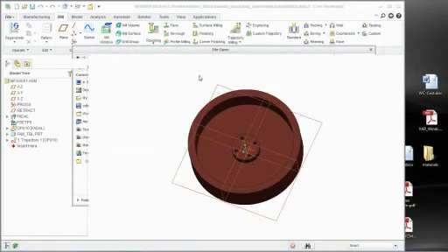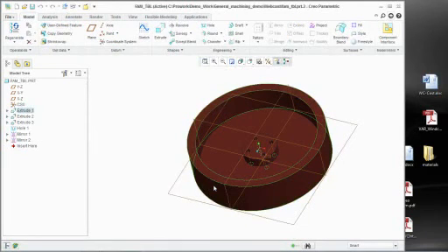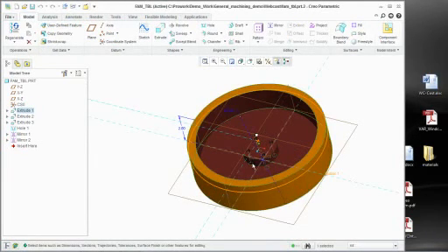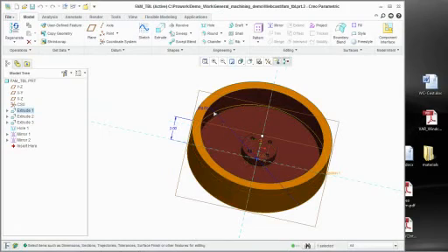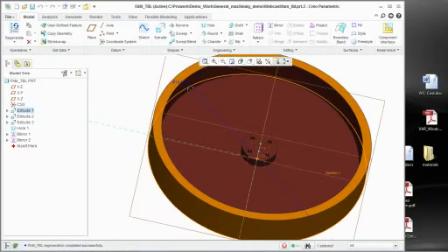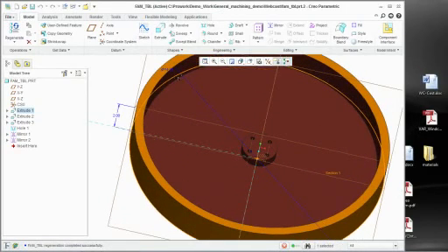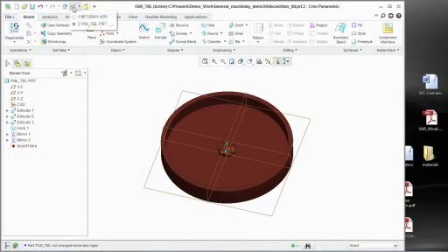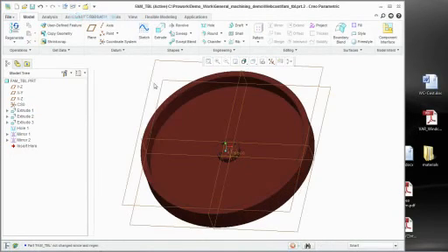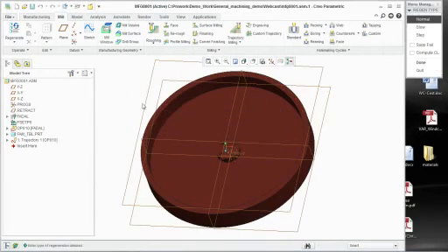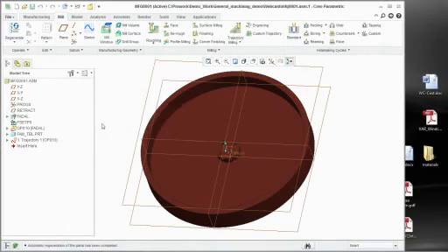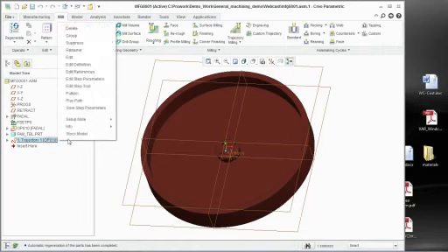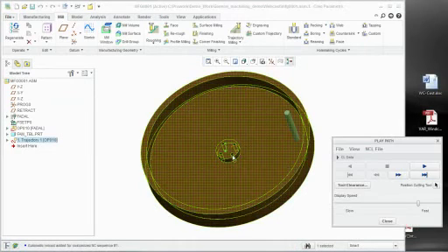And if I have a guy come in and say, instead of it being 8, I want it to be this big. Okay, this big right here. I can go ahead and regenerate those changes. I come back to my machining file, and then all I have to do is regenerate all of my toolpaths. So now what happens is all of the toolpaths adapt to the new geometry.